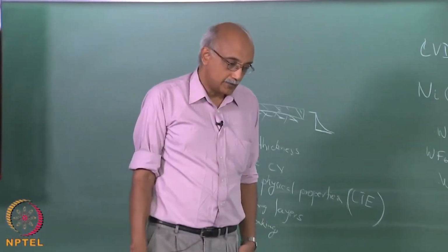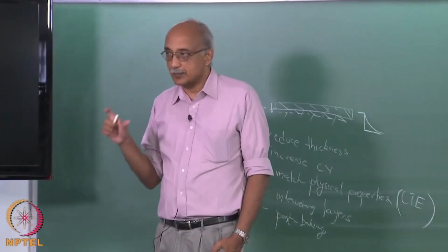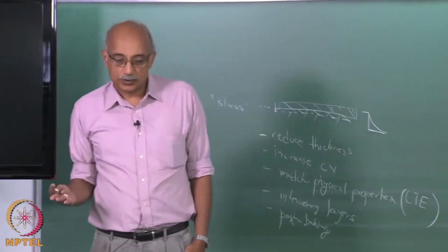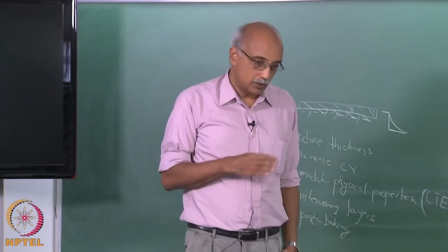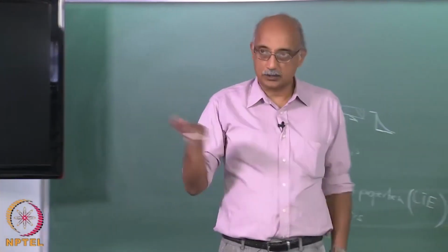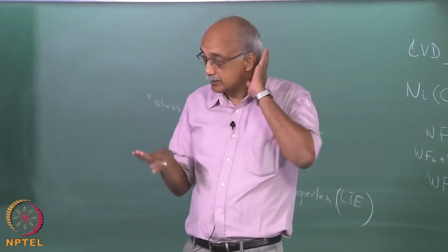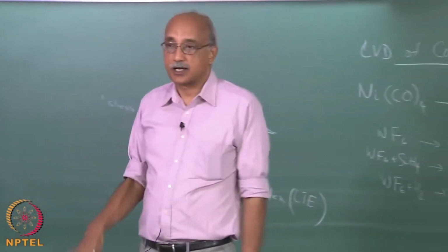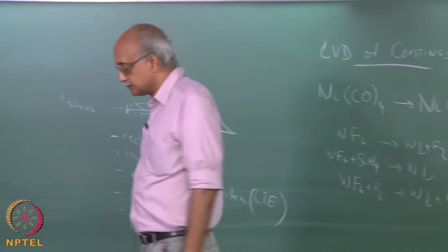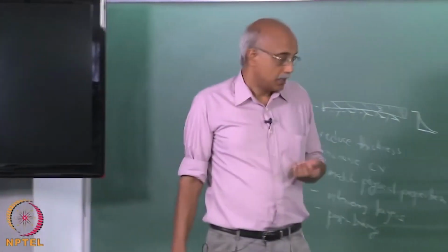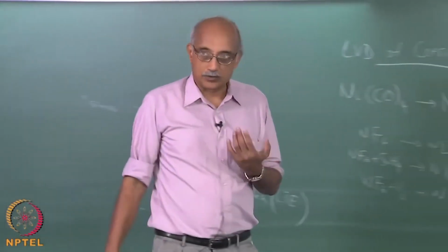They all have increased hardness compared to the base material that they are trying to coat. So, for tools especially, the primary requirement for the coating that goes on top is that it should be significantly harder so that galling does not happen, but at the same time it should have good frictional characteristics and wear characteristics.